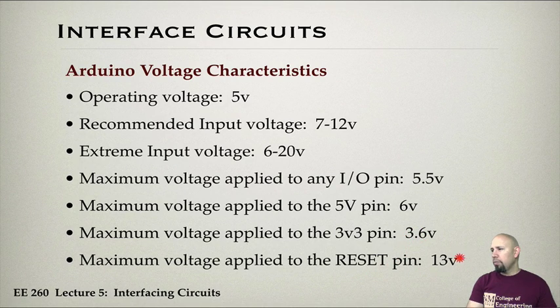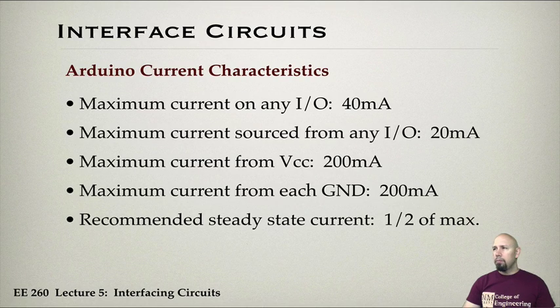And it turns out that you can apply voltage to the reset pin, and if you apply anything larger than 13 volts, I'm not sure why that's the case, but so it is, then you will have trouble. So these are the basic voltage characteristics. So maximums, you don't want to exceed those maximums.